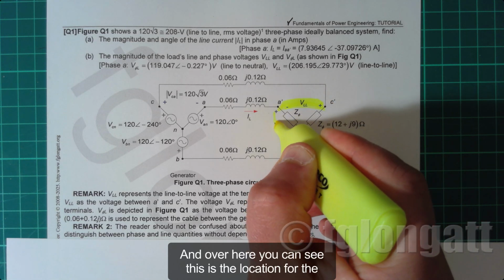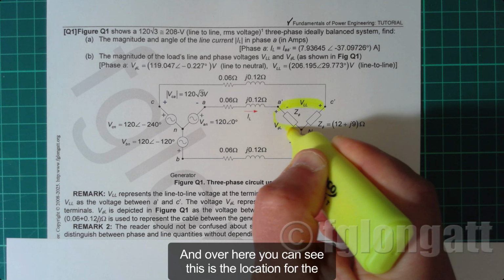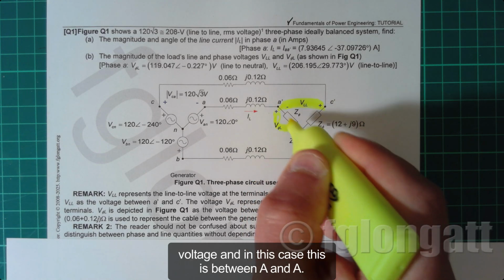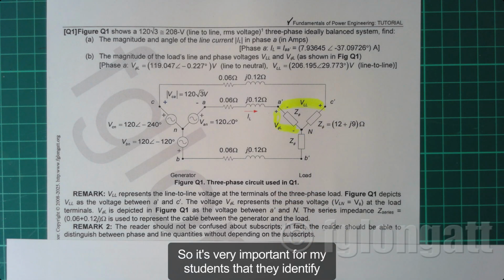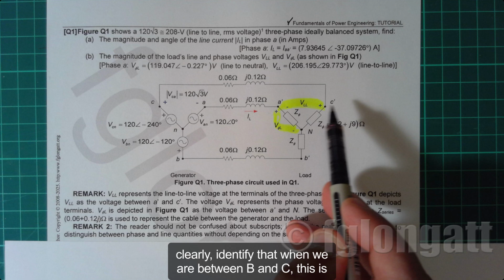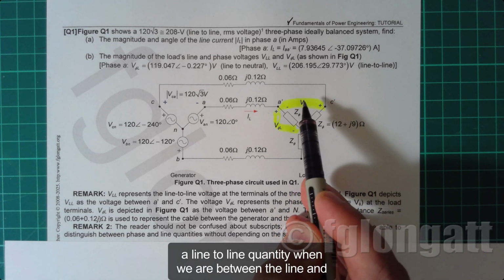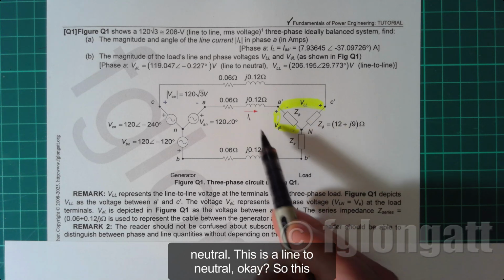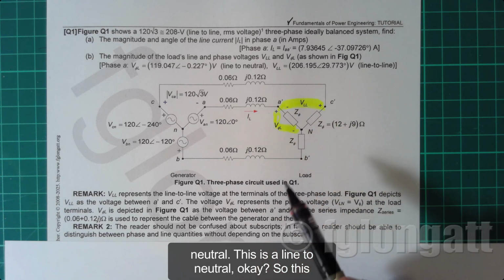And over here you can see this is the location for the voltage, and in this case this is between A and N. So it's very important for my students that they clearly identify that when we are between B and C, this is a line-to-line quantity. When we are between the line and neutral, this is a line-to-neutral quantity, okay?